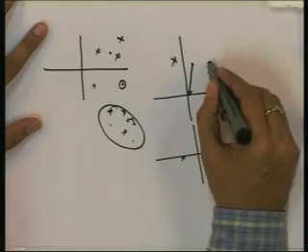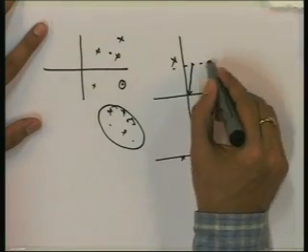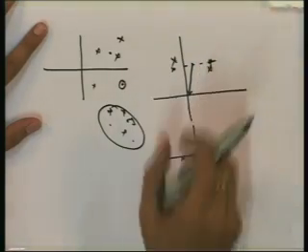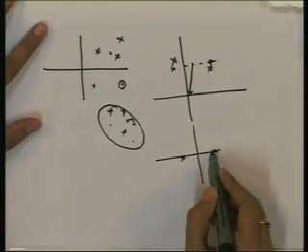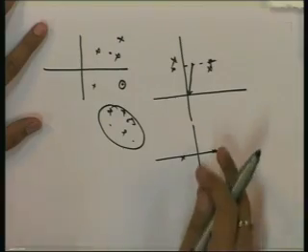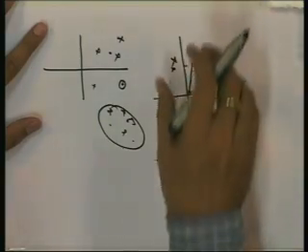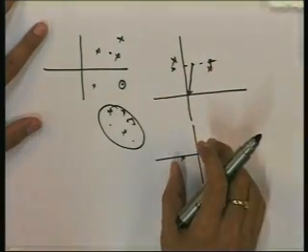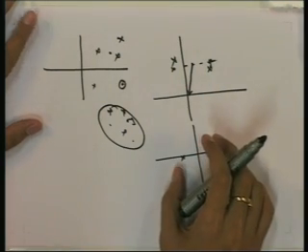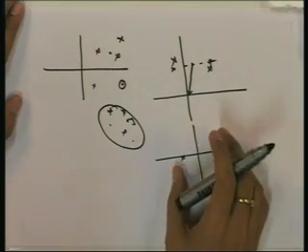So it will first go to a horizontal location, then we will translate this way. So we will bring the points here. Then it is the same as doing PAM. So instead of doing this, why not do this? This is a PAM modulation. We are familiar with this, we know how to demodulate, it is very simple.